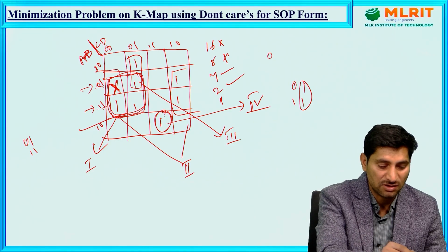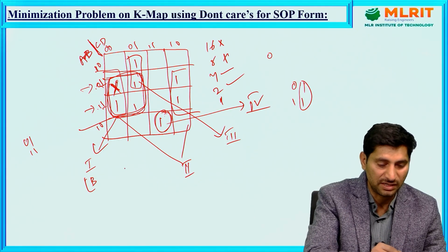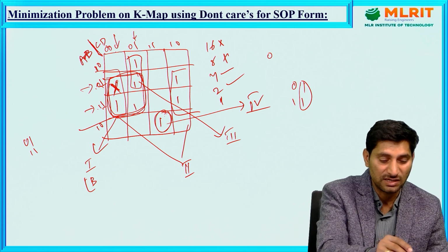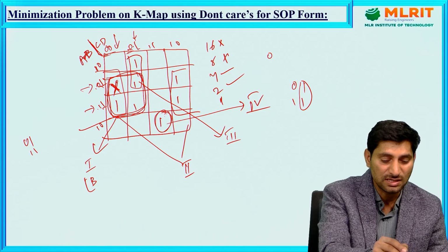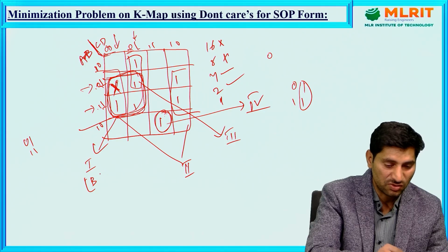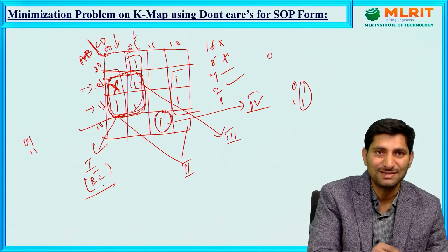So this one is common horizontally. Means here B term will come horizontally. For the same group, we have to see vertically also. So 0, 0, 0, 1 will represent. So this 0 is common for vertically. Okay. For this group. So 0 means here C bar. So from first group, we got term B C bar.